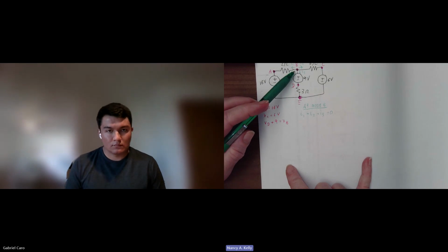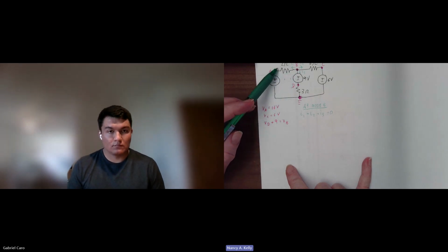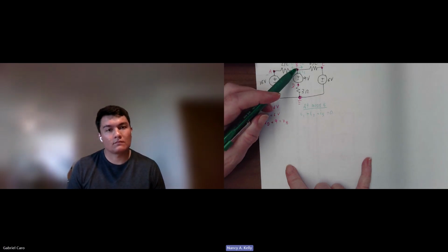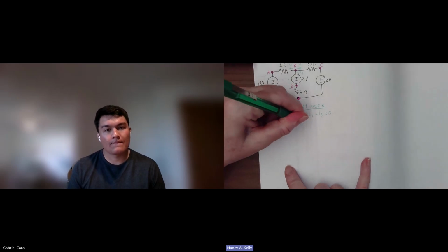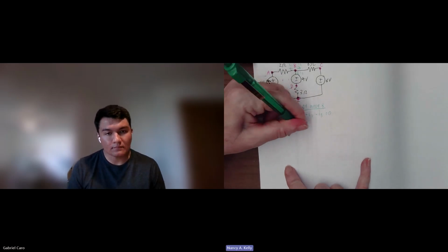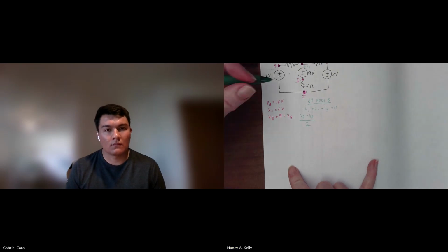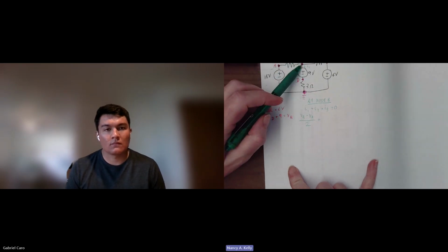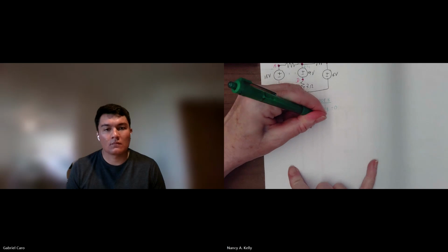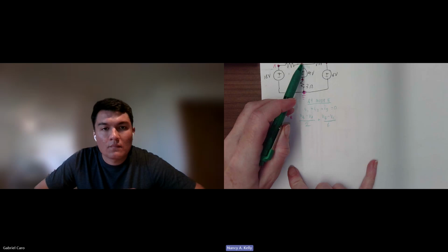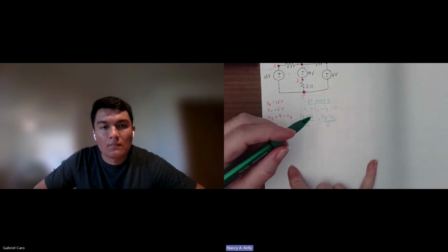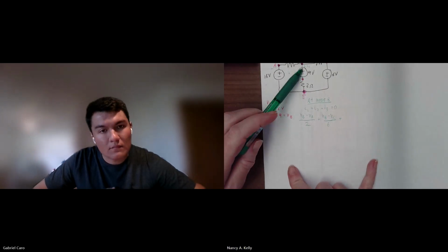So if I want to express I1 in terms of Ohm's law, I can do that because the current is flowing through the resistor here. I can say that I1 is VB minus VA, because that's the direction the current's flowing in, divided by the resistance, which is 2. Then I go to I2 and I've got VB minus VC divided by 6. Again, I2 is flowing this way. So I take the tail, the voltage there, VB, minus the other voltage, VC.